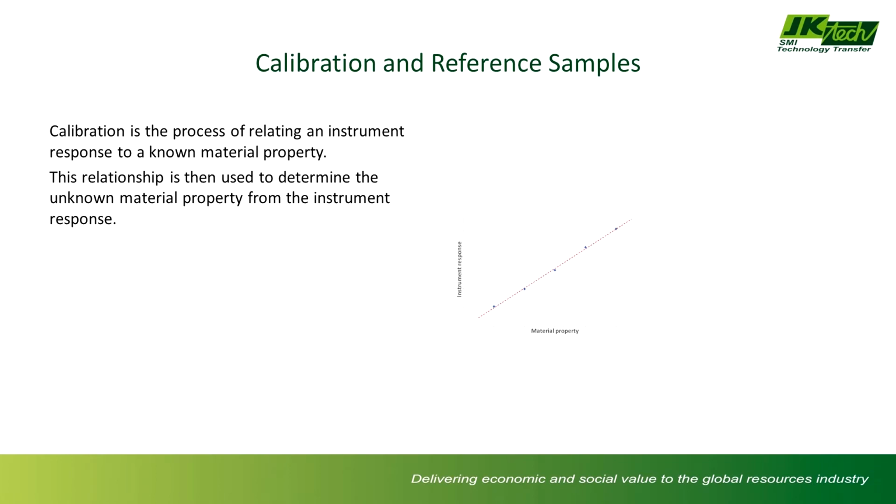In the example that I mentioned earlier, we're looking at electronic balances. The instrument response from the electronic balance these days is a voltage. You put your sample on the scale and the little piezoelectric crystals get squeezed and produce a voltage. What you'll have is a technician come in with a standard 1 kilo mass. He'll put that on the scale and go, that voltage equals 1 kilo. And with these reference samples, that technician's reference sample will be related to another one, which is related all the way back to the reference sample for a kilo, which is a platinum cylinder sitting in Paris. This means no matter where you go, you know that a 1 kilo at lab A is going to be a 1 kilo at lab B, because they can all get traced back to that initial total reference sample that is 1 kilogram.